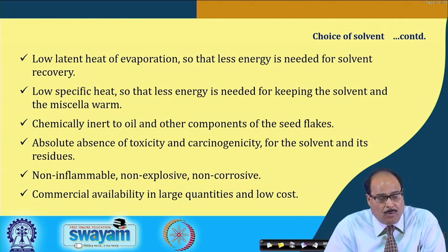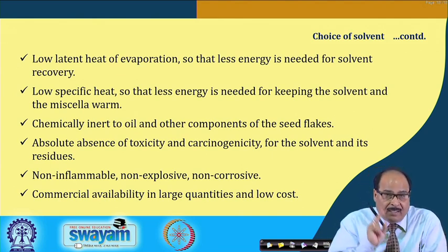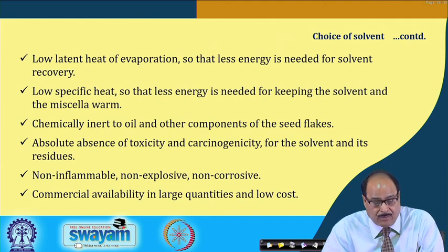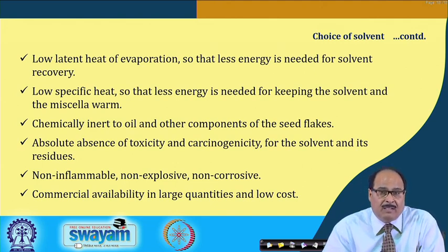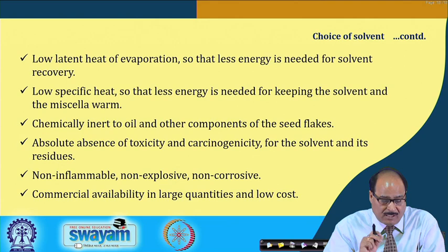Also, it should have low latent heat of evaporation, so that less energy is needed for solvent recovery. It should have low specific heat, so that less energy is needed for keeping the solvent and miscella warm. The solvent should be chemically inert to oil and other components of the seed flakes, and it should not be toxic. Very important: absolute absence of toxicity and carcinogenicity of the solvent and its residues.